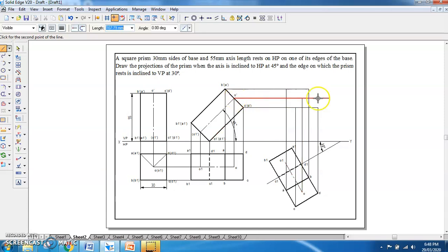You connect this O. Then you have got A1 here, A1 till this A1 here, like this, A1. Then you have B1 here till here it is B1. Then you have C1 here, C1 it is on XY till here. Then you have got T1 here, D1 from here until here you have got. So if you are having difficulty, first have the angle 90 set there, and then you can take it till here. Then you have O1 from here, O1 is here, so you can get again the angle 90 there till here, and you can connect it back to O1.